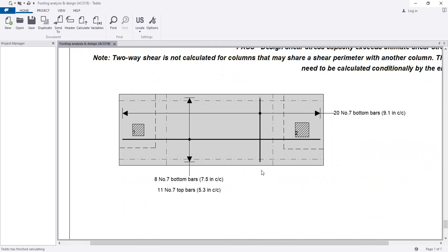And also we have to provide the reinforcement in the y direction at top, because for bottom here the requirement is there, that's why we have to provide reinforcement at top. So you have to just right click, calculate and provide that reinforcement.